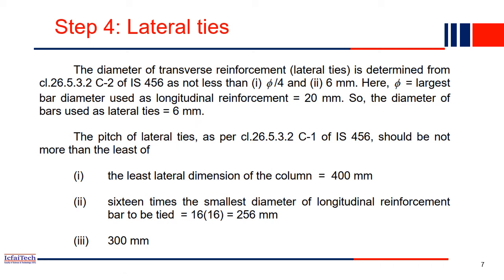In the tie bar also, now we understand. In the column, these longitudinal bars are also provided. What is the longitudinal bar? Here we provided 6 number of 20 mm bars and 2 number of 16 mm bars. Now we have to provide lateral ties also. These are the lateral ties. The tie bar dimension we understood: a 6 mm diameter bar. Now what will be the spacing of the tie? That we call the pitch of the lateral tie.